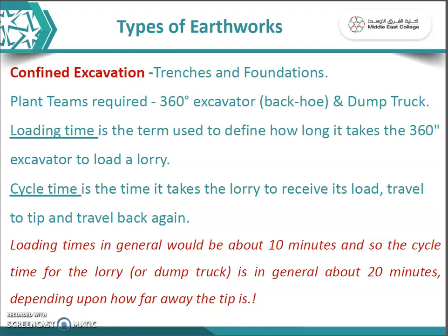One truck is loading, another truck is dumping. When that truck comes back, this truck starts loading, and the other truck goes for dumping. The loading time is generally 10 minutes, and the cycle time for a lorry is generally 20 minutes. It depends upon the type of soil being excavated. Whether it is loose, it may be fast. If it is hard, it takes time. It depends upon the size of the truck, and upon the distance from the loading place to the dumping place. These are the general factors to be considered.